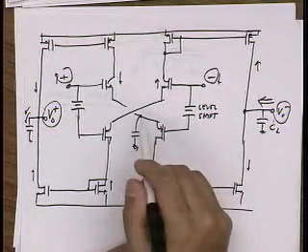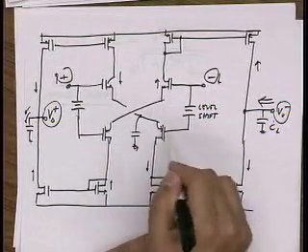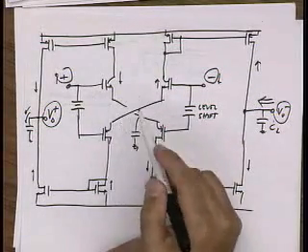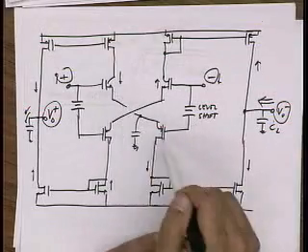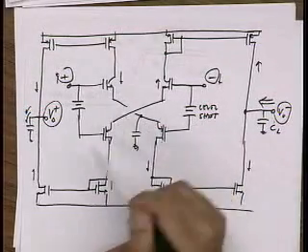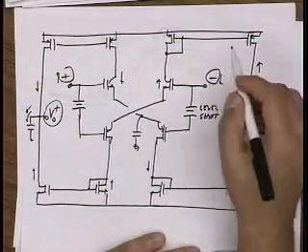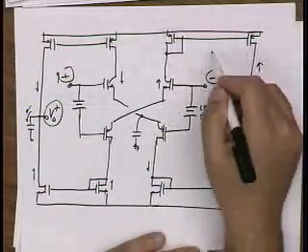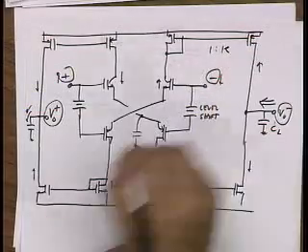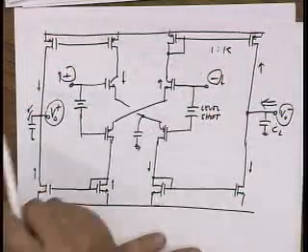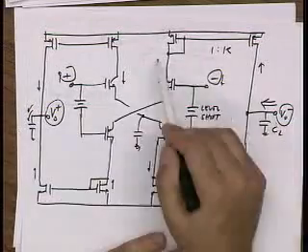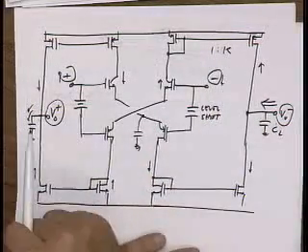The capacitance here is the CGSs of these devices. The impedances are like 1 over GMs of these devices. So if we're running these at low current, that could be our non-dominant pole. Also, I don't have to make this a unity gain mirror, right? I could actually have a current step here, let's say 1 to K. If this mirror has a step 1 to K, what's its frequency response?